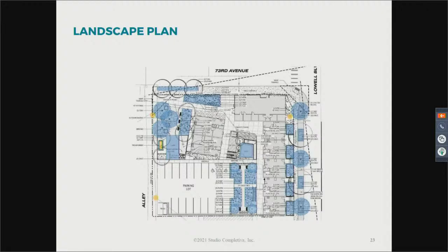It's going to melt in the undeveloped parts. It's going to go down into the soil. Everywhere else, it just finds a low point and pools or eventually dissipates or will make its way into that channel, and then into the storm sewer. So we don't flood because that was done.